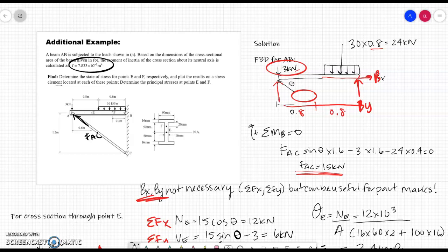So remember, the state of stress will be determined by where that point is, and we know that. We've spent a lot of time talking about transverse shear being 0 at the top and the bottom. There's no bending moment at the neutral axis, so we know different forces and different stresses are occurring across this section of the beam, and so now we can practice our skills at analyzing this type of problem. The first thing we always want to do is, of course, do our free body diagram for the whole beam to see what our loading is and what our support reactions are.